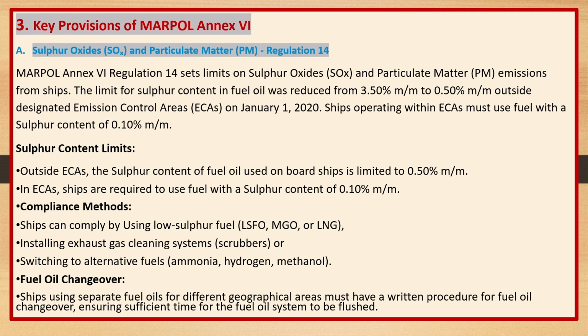Fuel oil changeover. Ships using separate fuel oils for different geographical areas must have a written procedure for fuel oil changeover, ensuring sufficient time for the fuel oil system to be flushed.